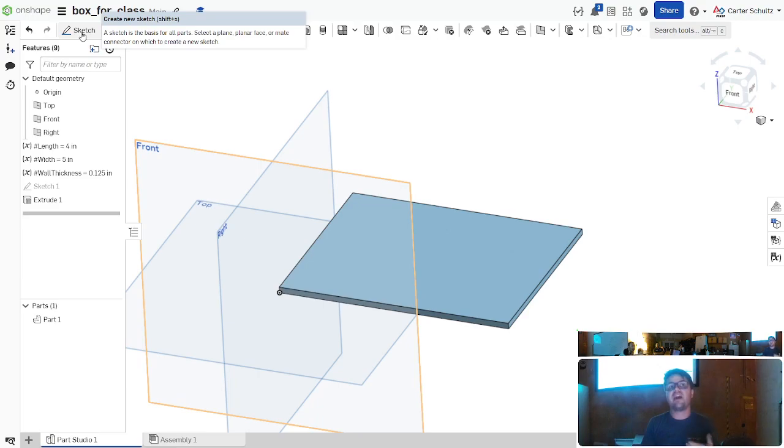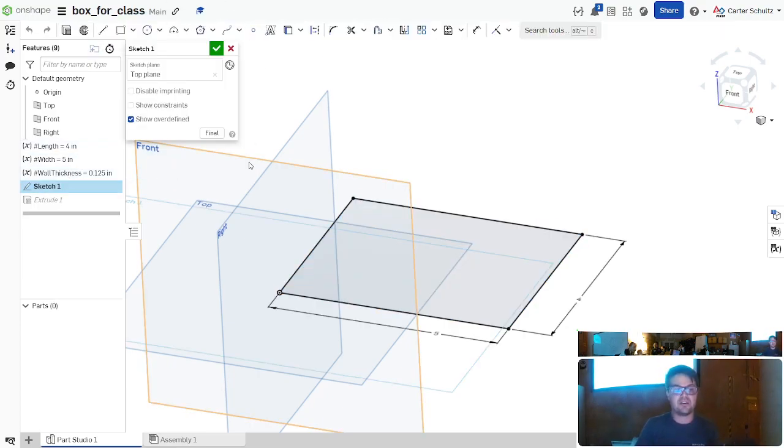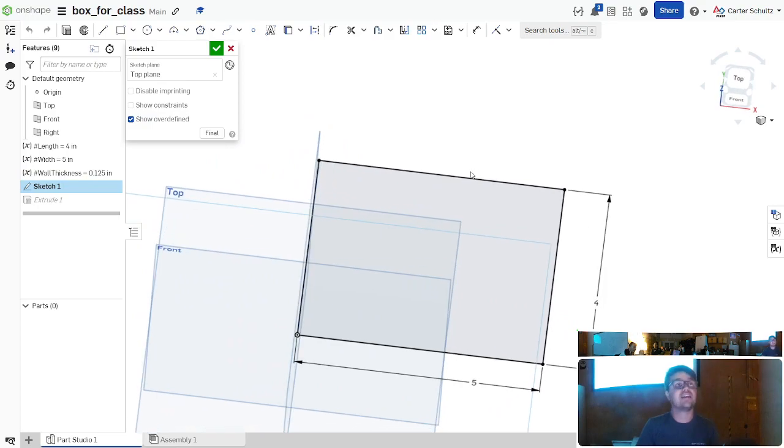When you do it that way, you get a lot more use out of the geometry tools. Things are stacked off of each other. I think it makes sense. So most of the advanced things that I've done have maybe 4 sketches, maybe 5 sketches at most, but try to keep your number of sketches down and use a lot of geometry in one sketch. So we're actually going to go back to our sketch 1 here, and I'm going to add the next thing that we want to extrude to this sketch.